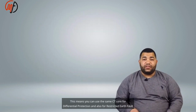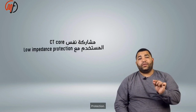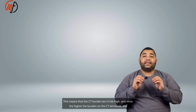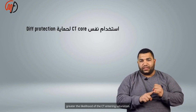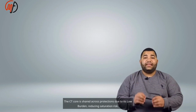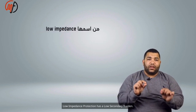This means you can use the same CT core for differential protection and also for restricted earth fault protection. The main reason we can share the same CT core across multiple protections is that it has a low burden. This means that the CT burden won't be high, and the higher the burden on the CT terminals, the greater the likelihood of the CT entering saturation. The CT core is shared across protections due to its low burden, reducing saturation risk. Low impedance protection has a low secondary burden.